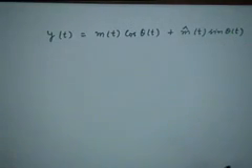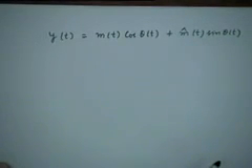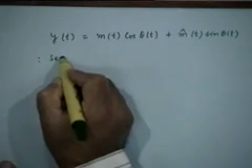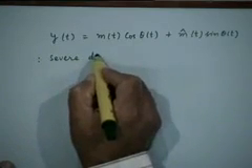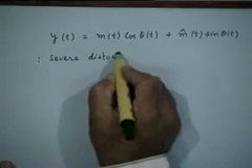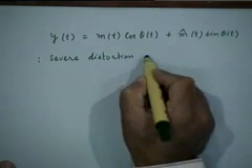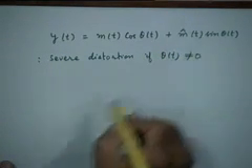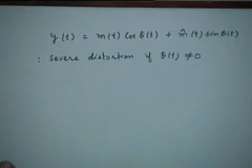So unless theta(t) is 0, this would lead to severe distortion in the recovered message signal, if theta(t) is not 0, right? So this is one small problem that we faced in the demodulation process in this case.